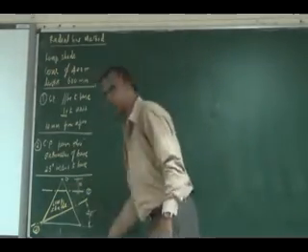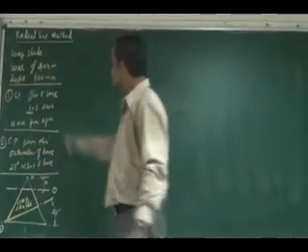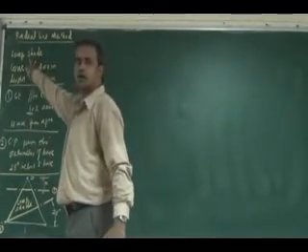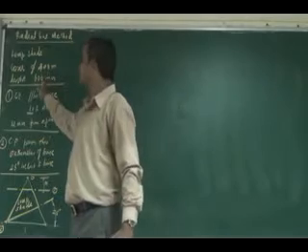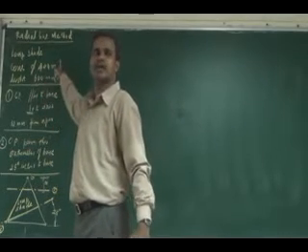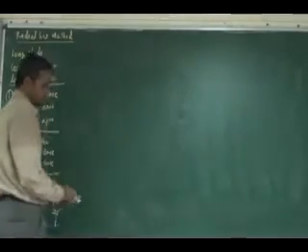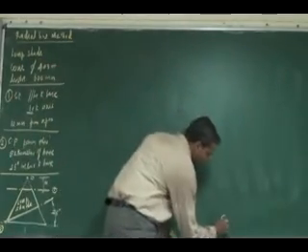So first you have to find the generator length, and for that you have to draw the projection. The cone has diameter 400 and height 600, so you have to use a scale. What scale should you use? 1:10 again. So the scale is 1:10.